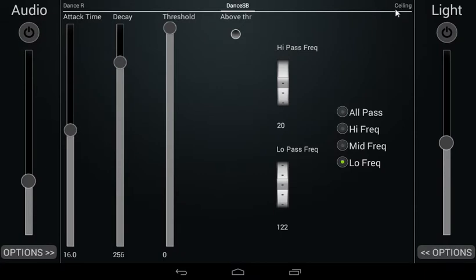So what we see here are a high-pass filter at the top and a low-pass filter at the bottom. The high-pass filter at the top only allows the high frequencies to pass through it, hence it's also sometimes called a low-cut filter. The low-pass filter at the bottom only allows the low frequencies to pass through it, hence it's often called a high-cut filter. We can choose the cutoff frequency of the filters by sliding over the vertical bars. The values are indicated in Hz and can be set anywhere between 20 Hz and 20,000 Hz. By selecting one of the four options from the menu on the right, we can define if one, both or none of the filters are active.